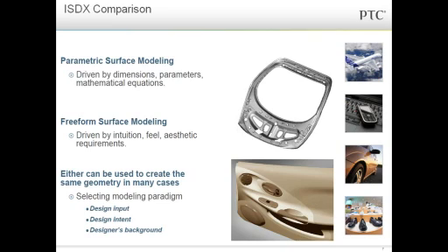Now, in saying that, we shouldn't take along the idea that freeform surface modeling can't be tied parametrically to other objects. Just like I can tie freeform surfacing curves just to keep them out in space, I actually can attach them to other parametric curves, to sketcher curves or just the fill surfaces. And as those parametric objects change, my freeform curves and surfaces change also.